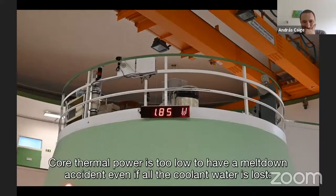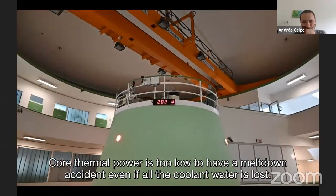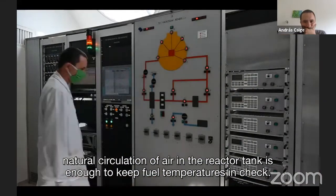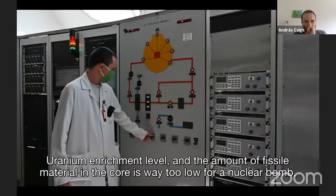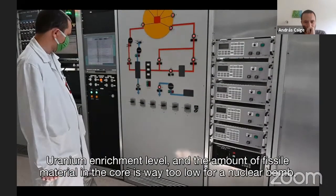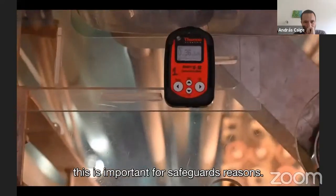Core thermal power is too low to have a meltdown accident, even if all the coolant water is lost. Natural circulation of air in the reactor tank is enough to keep the fuel temperatures in check. Uranium enrichment level and the amount of fissile material in the core is way too low for a nuclear bomb. This is important for safeguards reasons.